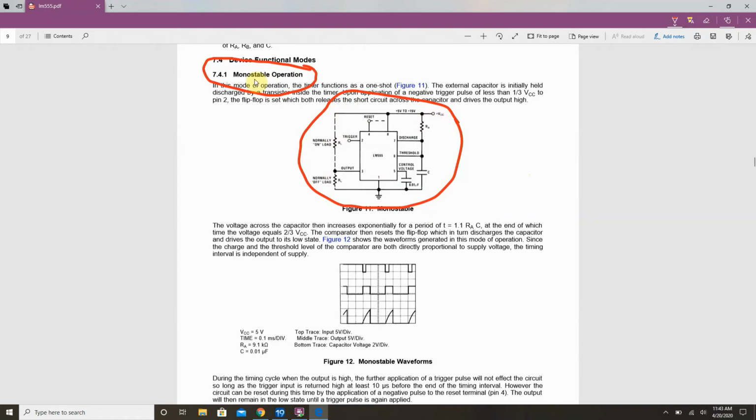You'll notice that the monostable only has one R and one C. And by the way, this C is an electrolytic. We control that pulse that I mentioned in the intro with these two values. Okay? And I'll explain that in just a minute. Pin 5, I said earlier, we're just going to hang a filter capacitor off of that to ground, and it shows it right here.